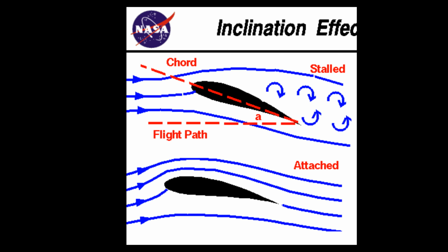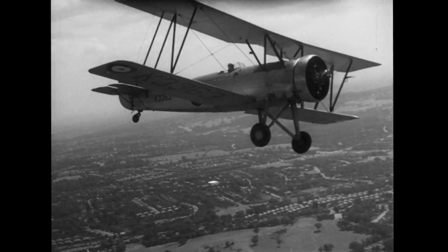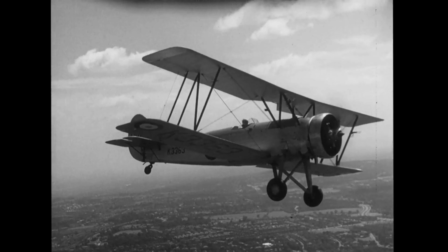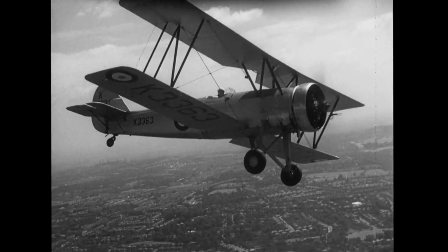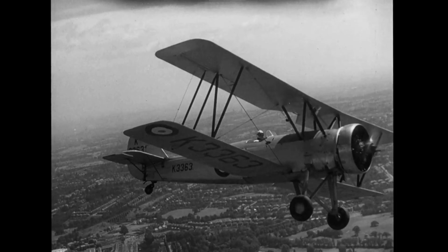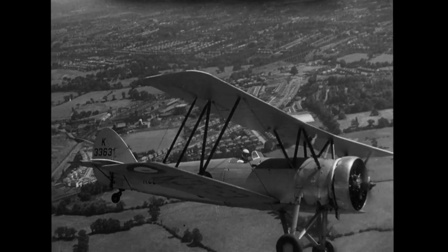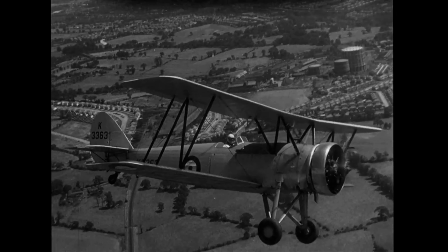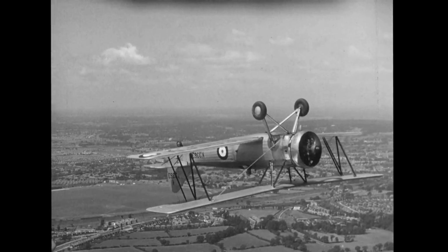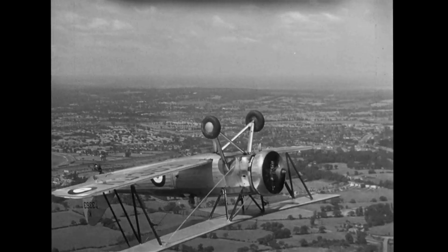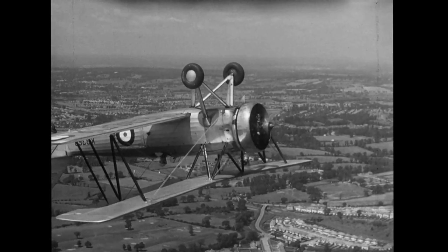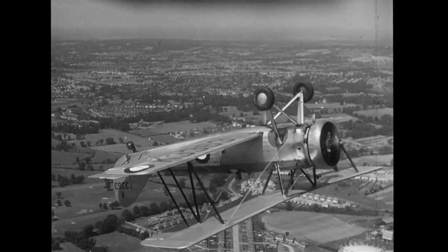Lift is actually produced by airfoils, aka wings, deflecting air. The air changing direction is an action force, and lift is the reaction force. Most wings are curved so that the air will be deflected downwards. However, this doesn't answer our question of how planes can fly upside down. Not all planes can fly upside down. For example, an Airbus would probably not be able to fly upside down. Fighter jets, on the other hand, can fly upside down because during upside down flight, they maintain a high angle of attack so that the wings still deflect the air downwards.